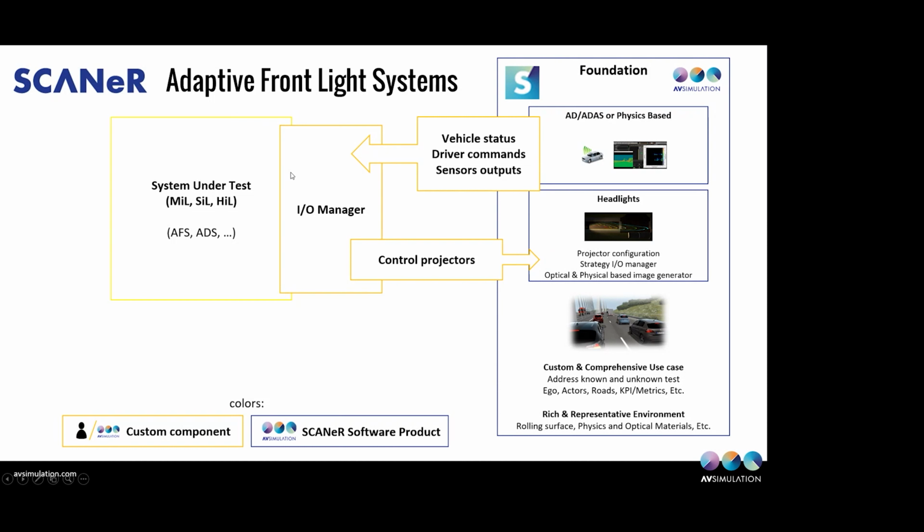If you are using software in the loop, we're able to directly incorporate compiled versions of your software into the simulation loop. And if you want hardware in the loop, the real-time targets pack allows you to connect to different kinds of networks, such as CAN networks, in order for it to feed information to your vehicle.